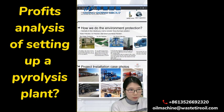The syngas can be used to heat the reactor for saving your heating fuel. But if you use it directly to heat the reactor, it may produce a bad smell. So before we use the syngas to heat the reactor, we have the syngas purification system to purify the syngas, so we can control that there's no bad smell.